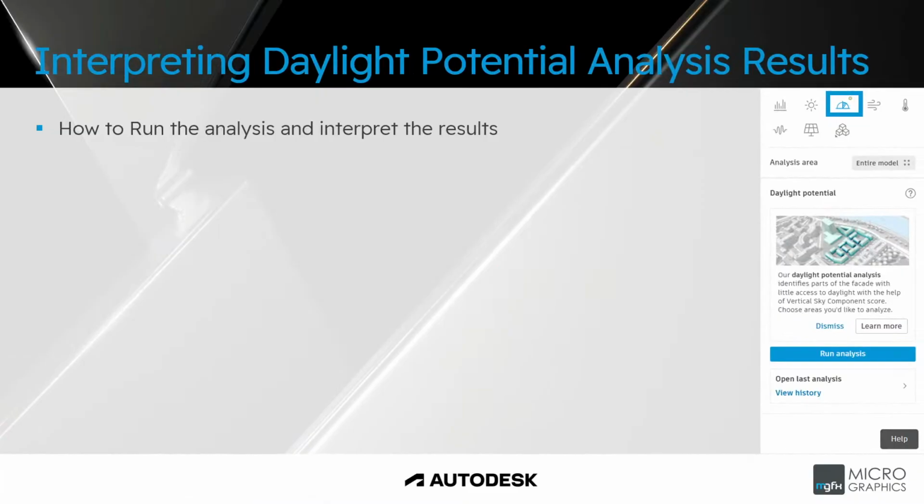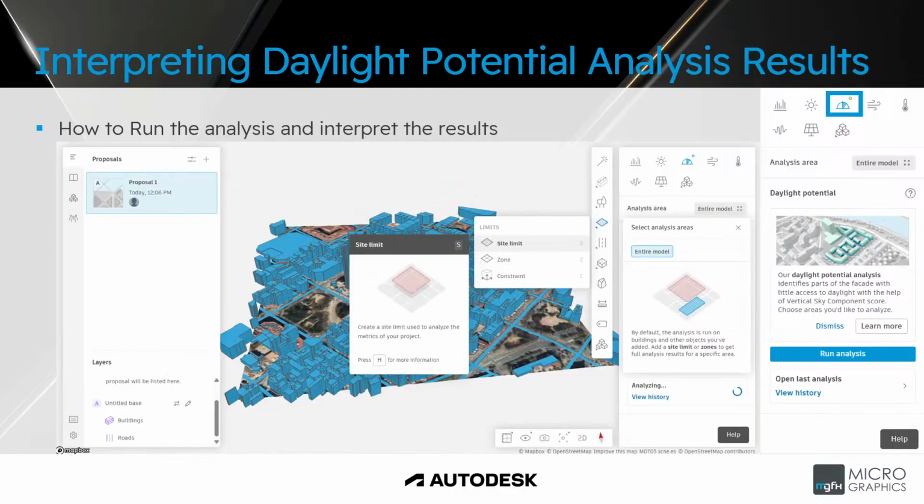Okay, so interpreting daylight potential analysis results. In a project, select daylight potential from the right pane menu. To run the analysis, select one or more site limits or zones or the entire model from the analysis selection menu to define the area where the analysis will be computed, and then click Run Analysis.